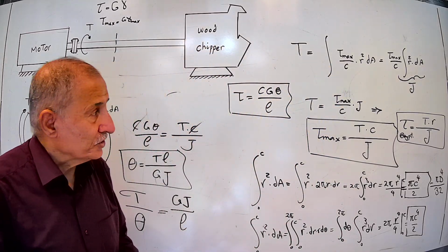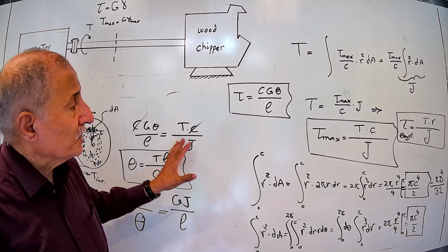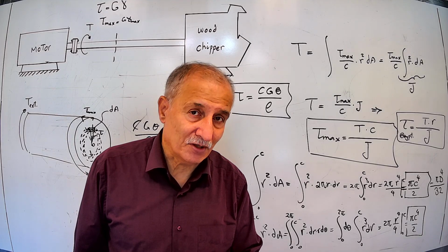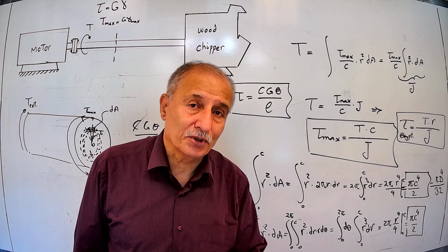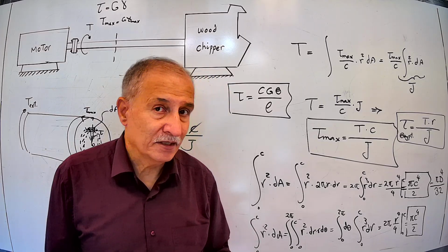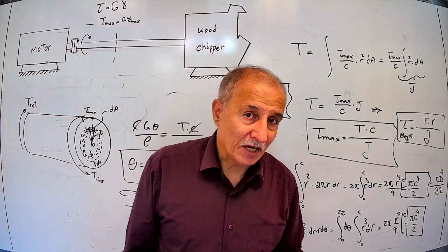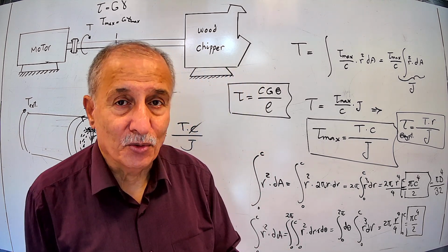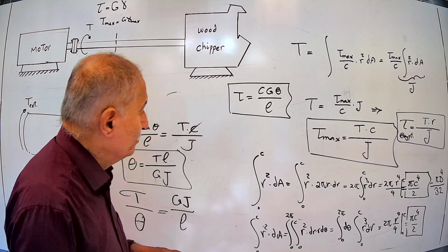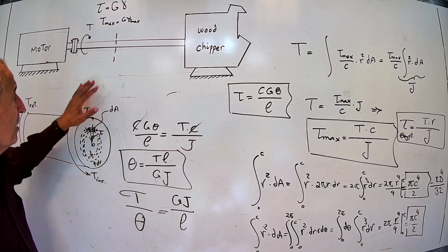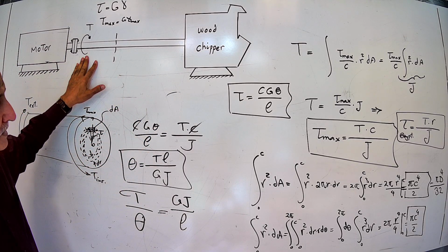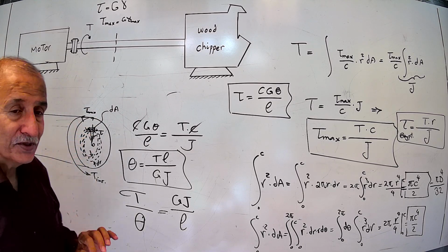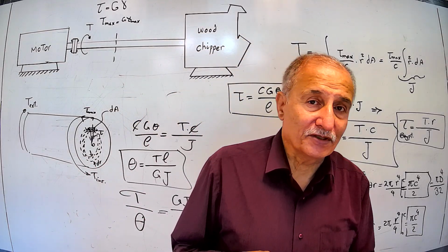Later, we consider when the shaft is hollow and not solid. Why do we need a hollow shaft for torsion? If there is only one external load, and it is only torque, with no bending and no transverse or shear load, then there is no need to put material at the center around the longitudinal axis of the shaft.